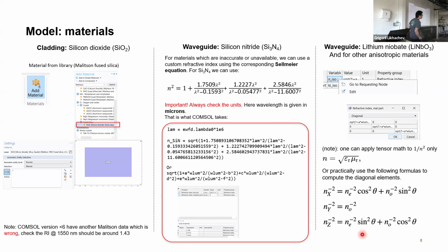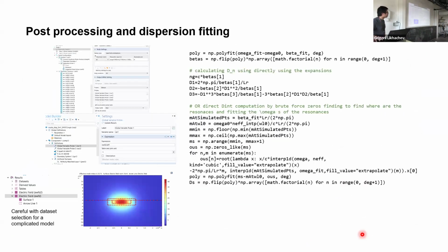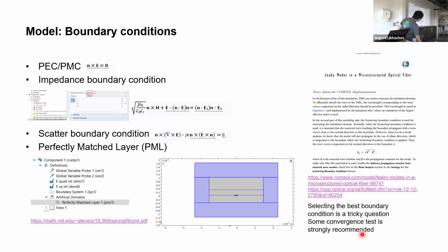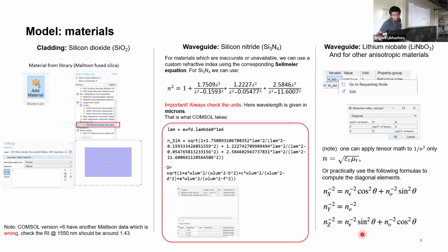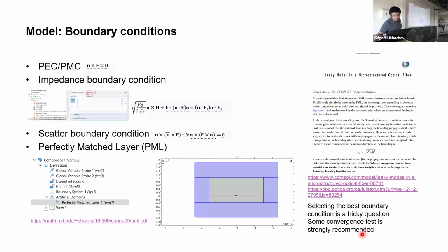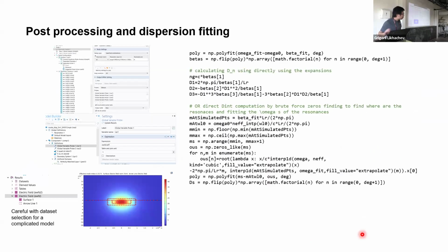Yes. Can we find the effective mode area with the solution? Yeah, for sure. This is what you can do in the post-processing. I think in the model I sent you, there is something similar. Once you have the mode profile, you can not only plot it but also define arbitrary integrals.